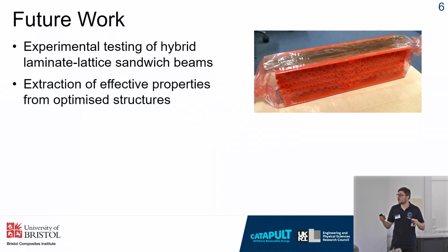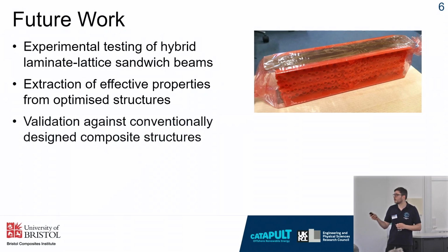Once we've got this, we can extract effective beam properties. If we look at a longer beam structure, you can approximate your bending stiffnesses and things like that, and then you can put that into another model, a 1D model, and look at the responses under loading, which will be relevant in a second.